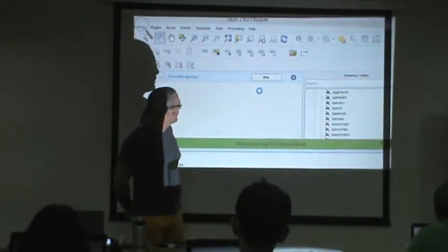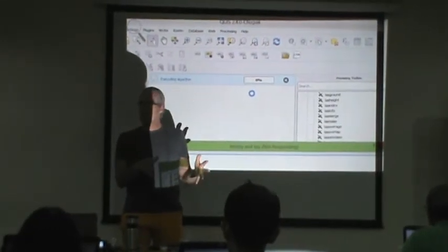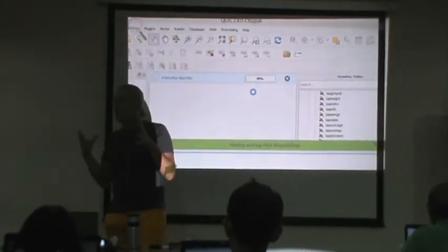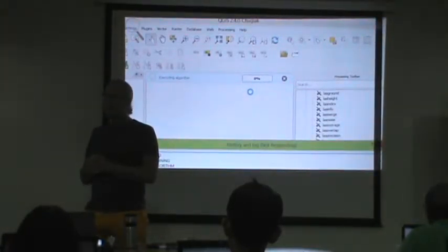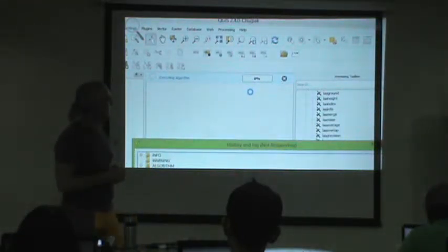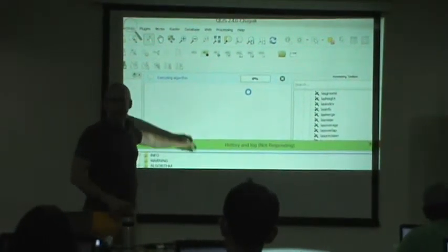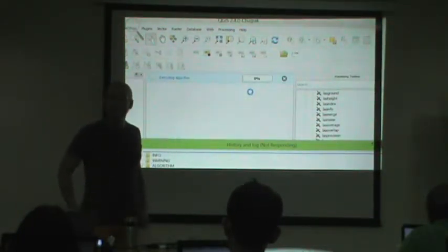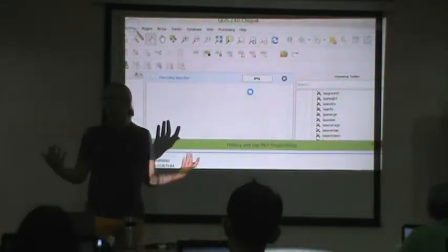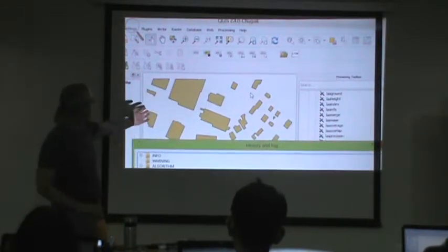in this workshop, and it was loading a bunch of flight lines, merging them into one. Then it was doing ground extraction, then it was classification of buildings, and then it was extracting the building footprints, and at the very end, it was loading that onto the canvas and displayed it in QGIS, all in one go. And there's a graphical interface where you can set up this model. Now, I'm in no position to teach that right now because I was a student myself in that course, and wow, but it did work.